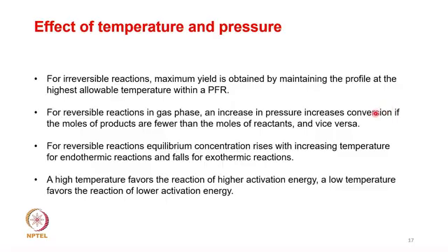temperature and pressure are key variables in a reaction. For reversible reactions, the maximum yield is obtained by maintaining the profile at the highest allowable temperature within a PFR. For a reversible reaction in gas phase, an increase in pressure of course increases the conversion if the moles of products are fewer than the moles of reactants, and vice versa. So if the moles of the products are reduced, it actually favors the conversion, and vice versa.